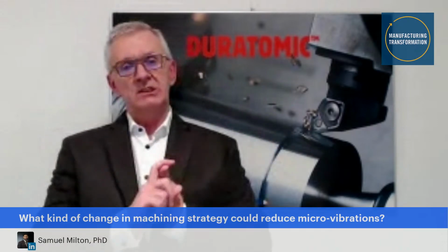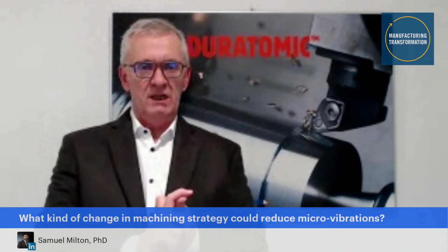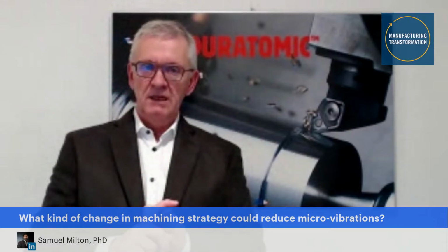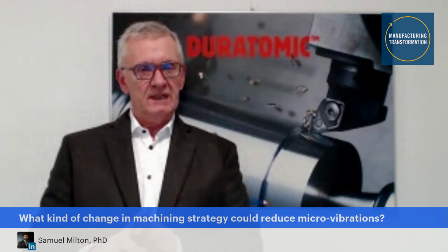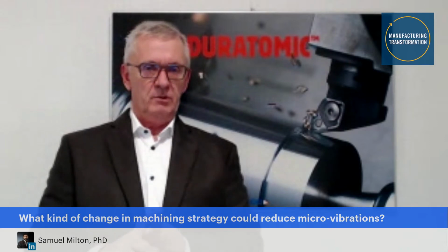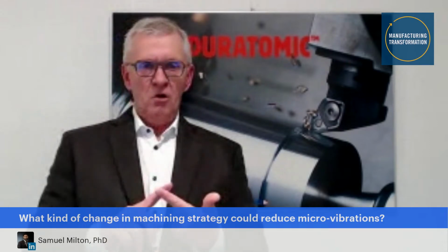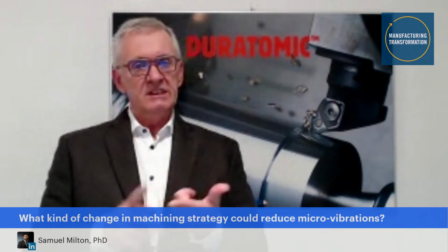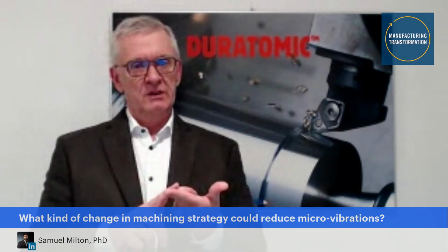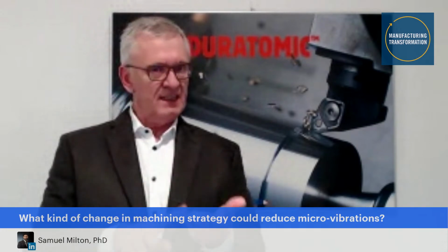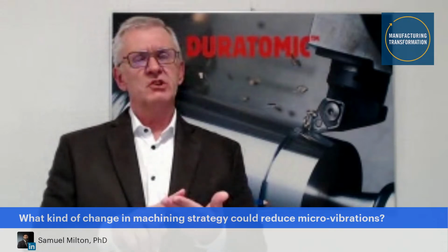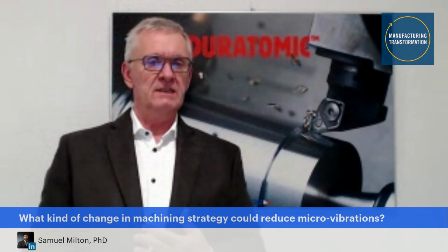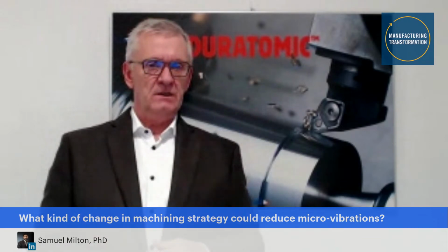Dynamic machining is a strategy that will minimize variations in cutting forces, at least in size, and that will lead to lower tendency for micro vibrations. Stronger geometries will increase the average cutting force, but decrease variations. So stronger cutting edges, more negative acting cutting geometries, minimize the risk for micro vibrations.